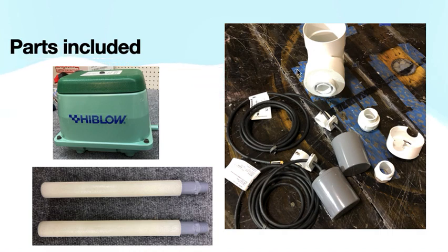And last but not least, this is the 4-inch sewer tee paired down to that 1-inch PVC, and that's where that vent line is going to go back from the reverse flush headworks to the inlet of the first tank. So that's that. Like I said, there are more parts included, but these are the ones that we've been talking about that we'll have there in that kit.